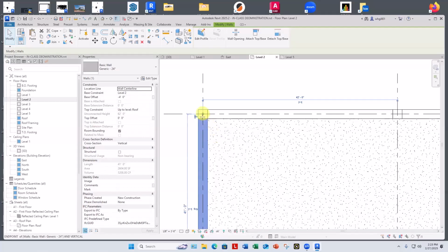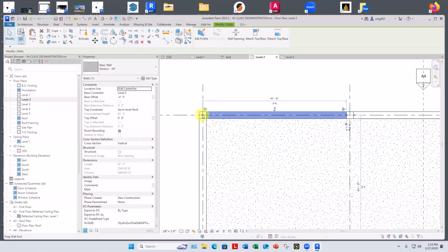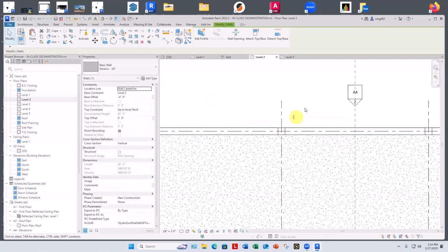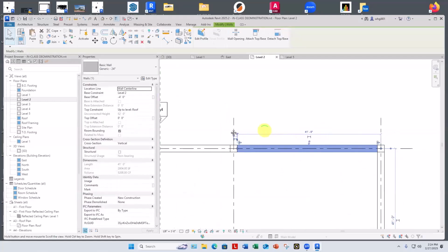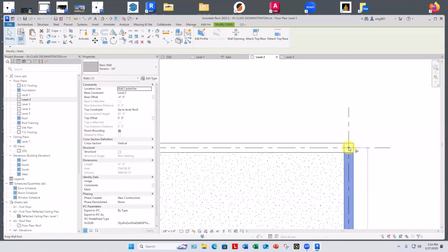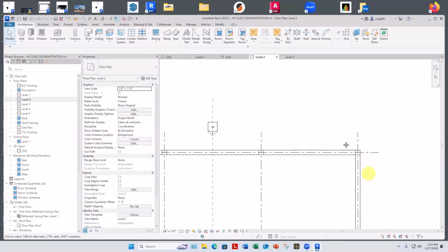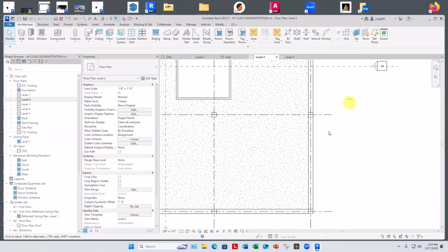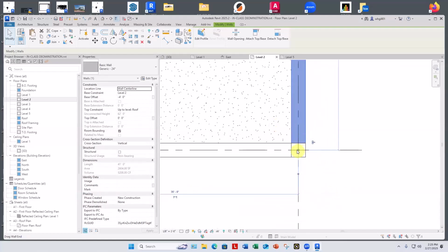I'm doing it this way just to know that there's no overlap going on. Anytime I see a problem, I'm using this right click and disallow join and dragging it down so my control point is right here. All these should be drawn between the columns. Disallow join. It seems like at the corners is where they do that most. Yeah, all the corners seem to mess up.